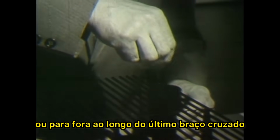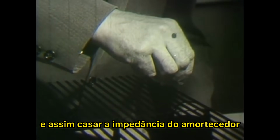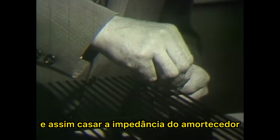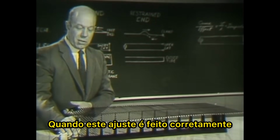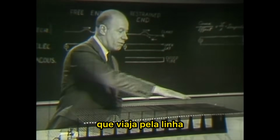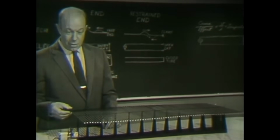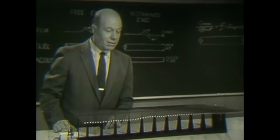By sliding this dash pot in or out along the last cross arm, I can control the counter torque with which it resists the displacement of the medium, and thus match the impedance of the dash pot to the impedance of the transmission line itself. When this adjustment is properly made, the dash pot absorbs all the wave energy that travels down the line, and as you can see, hardly any perceptible reflection takes place.